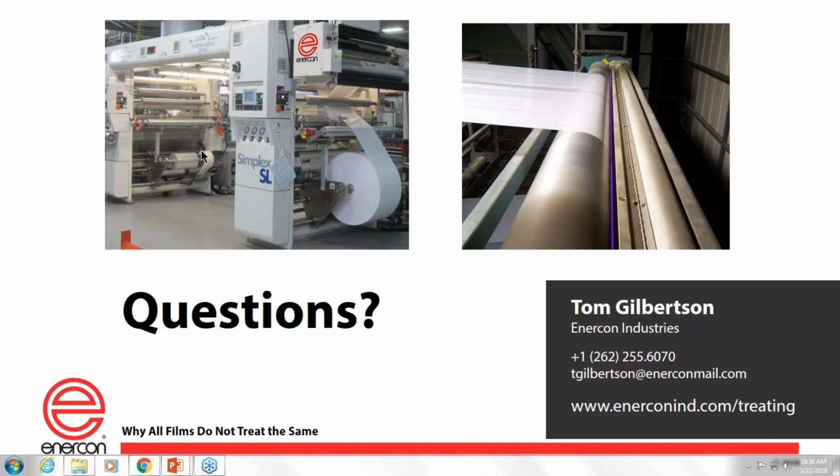Here's a question regarding humidity. Is the impact more on high humidity environments or low, or both? Well, high humidity has more impact not necessarily on the dyne level of the material, but the humidity in the air has more impact on the performance of your equipment and the maintenance of your equipment. So for example, during the wintertime, if you're in the southeast, let's say, in the United States, the air is more dry, and likely your corona treaters don't suffer many maintenance issues relative to that.